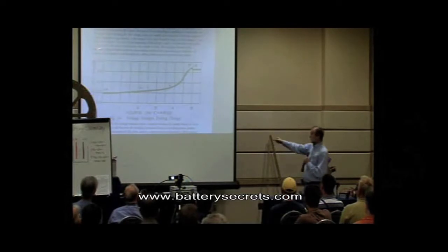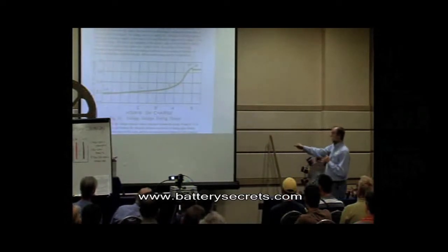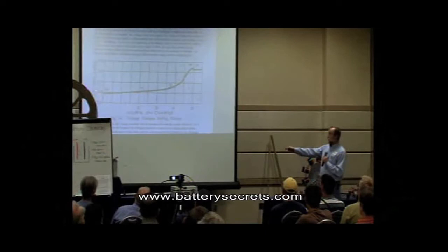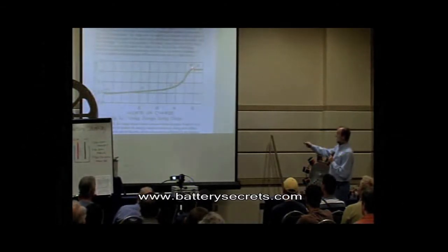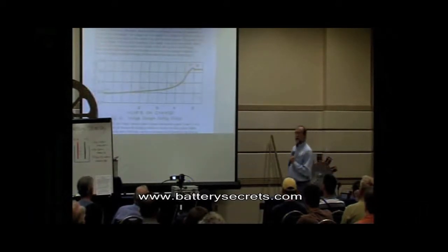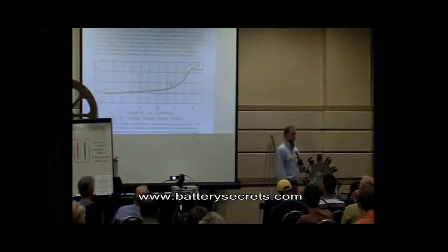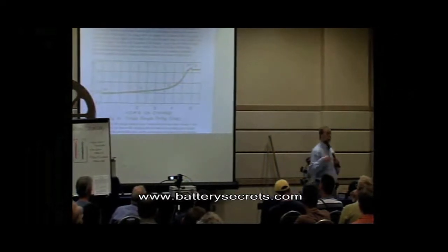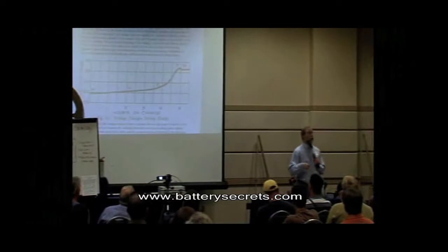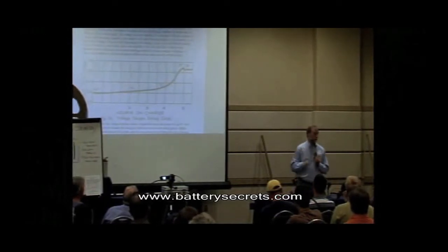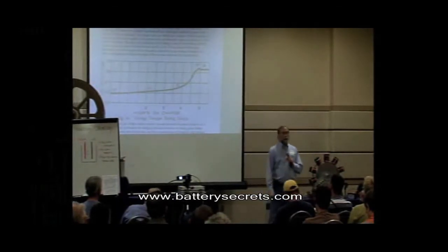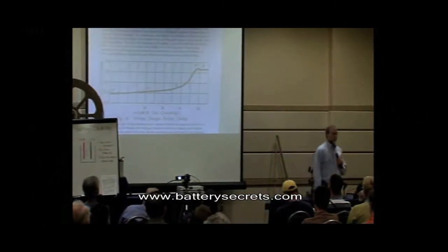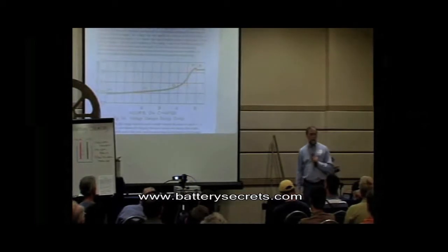Take a look at these numbers here. And take a very good look, because the fact is that this chart says a lead-acid battery is done at 2.7 volts per cell. A little bit of quick math times 6, 16.2. The battery isn't done until the voltage reaches 16.2.